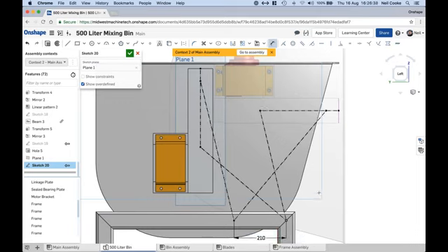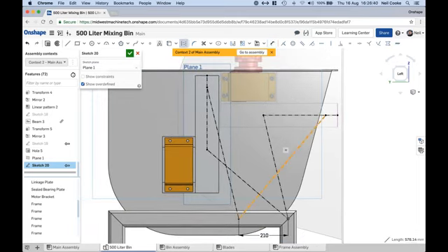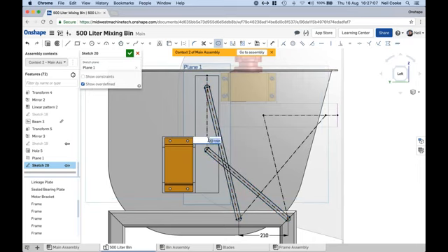Okay, so if we make that 210 millimeters, it does mean that these linkages just come out as bizarre numbers, 576.14 and 453.88. That's kind of inevitable. Whichever dimension you fix, at least two others are going to be a little bit obscure. Okay, that's not really a big deal. All we need to do now is just create the linkages like we saw previously. So we'll create two slots on here, and let's just make those guys a little bit bigger.